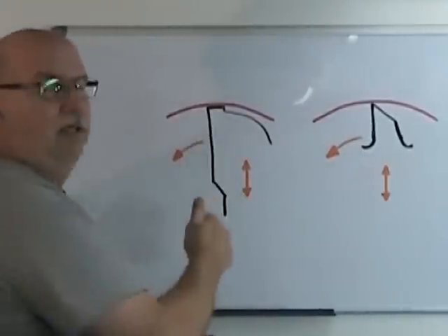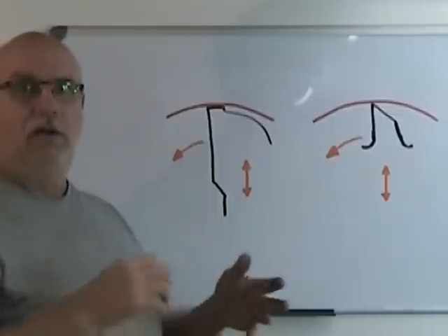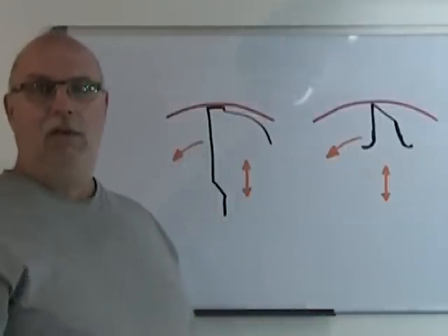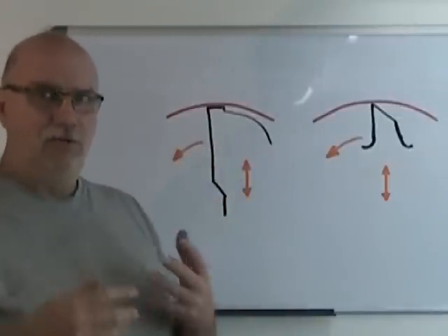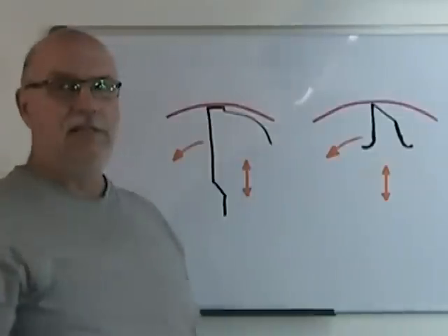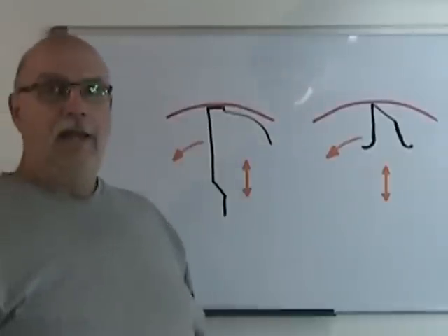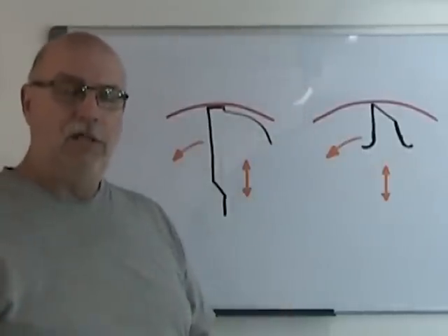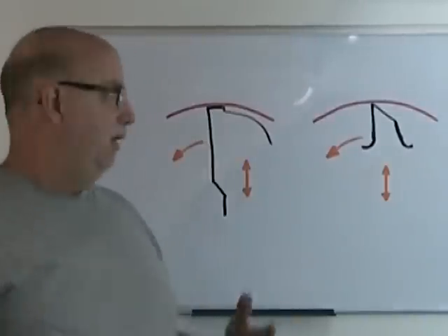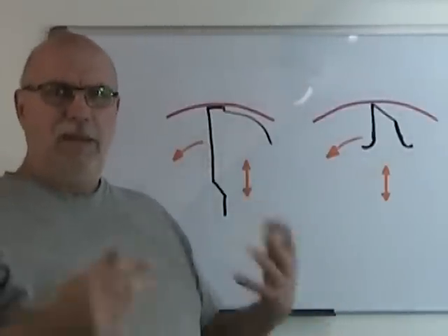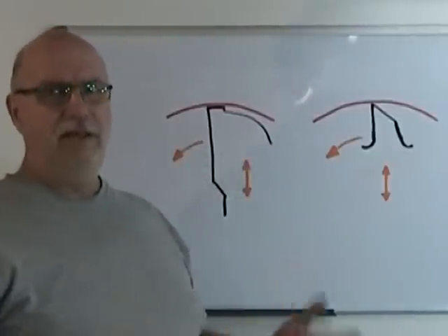If this tool actually cut a hole its exact diameter, this tool would jam into that hole. It's not a problem because drills, as mentioned before, always cut their holes a little oversized. This tool is made to lightly shave a hole bigger and to maintain the best diameter possible. And for that, we need this cutting edge. But that also implies that there's a major difference in how we use both these tools. And there is a major difference.